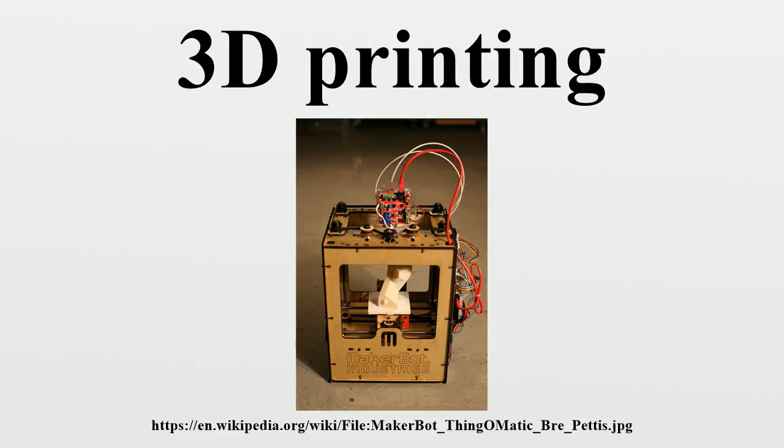Another method consists of an inkjet 3D printing system. The printer creates the model one layer at a time by spreading a layer of powder and printing a binder in the cross-section of the part using an inkjet-like process. This is repeated until every layer has been printed. This technology allows the printing of full-color prototypes, overhangs, and elastomer parts. The strength of bonded powder prints can be enhanced with wax or thermoset polymer impregnation.